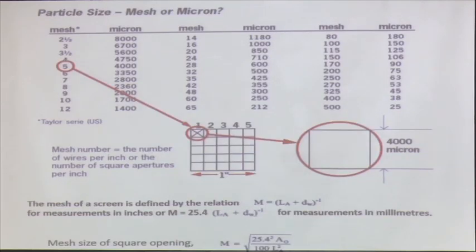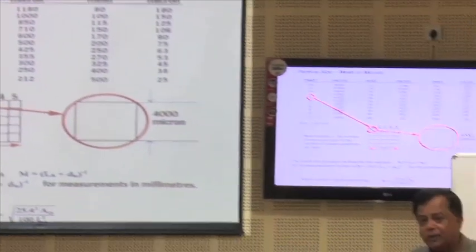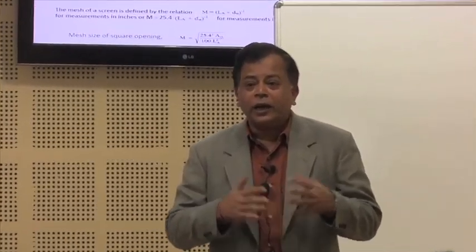Now I will answer some very practical questions that I asked. Suppose I have 1 kilogram of material, how do I select the topmost sieve and the bottommost sieve? The answer is you have to first do trial and error, some guesswork. You take only one sieve, say 5 millimeter, pour the entire material into that, and sieve it with your hand. If you see that the total material retained on the sieve is not more than 5% of your total population,